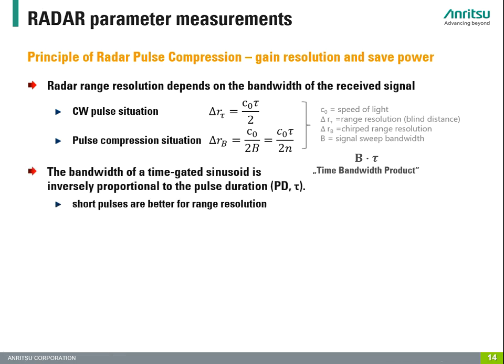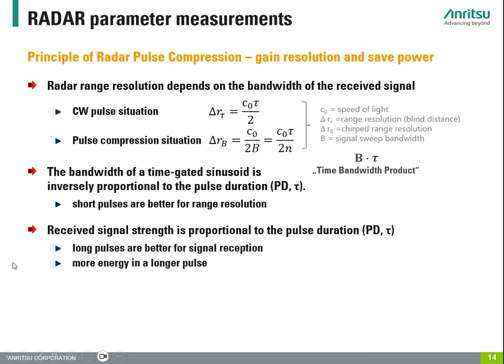Let's recap. Short pulses are better for range resolution. Received signal strength is proportional to the pulse energy. This means RF power times pulse duration.